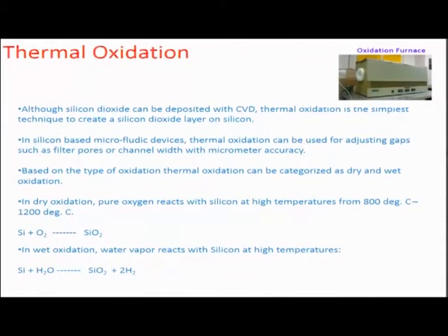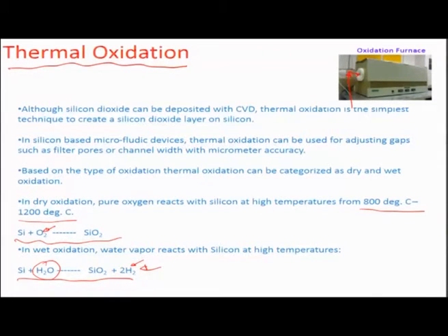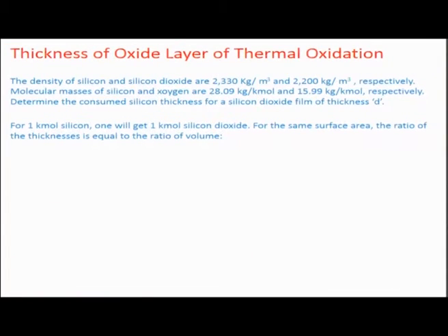There is another very interesting thermal oxidation process where you are using thermal energy to excite the crystals on top of the silicon wafer and then passing oxygen molecules close by, whether in dry or wet state. In the wet state, the reaction rates are very high, and typically the silicon wafer, for creating a condition where it can start entrapping the oxygen, needs to be heated to 800 to 1200 degrees Celsius in a quartz tube. The wafers can be stacked inside this tube, and the furnace can be set up at a high temperature, and the oxygen flow at dry condition, or passed through a bubble trap so that it has water vapor, can be passed through the tube and around the wafer at a higher temperature, so that there is diffusion of molecular oxygen into the substrates.